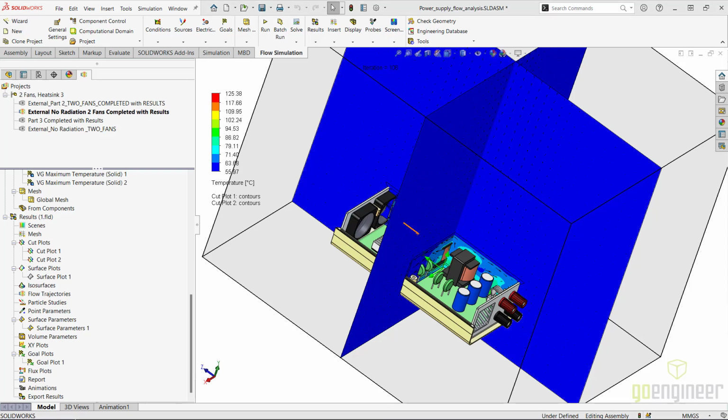So moving forward here, the decision will be to keep radiation on, in this case, just to make the overall model more accurate, but we'll actually use another, more applicable radiation model that comes with the HVAC module in Flow Simulation. Although we're not reviewing results for the other components necessarily in our project, this mechanism of heat transfer could be important for future investigation of those components, and so we'll use the more applicable radiation model here next.